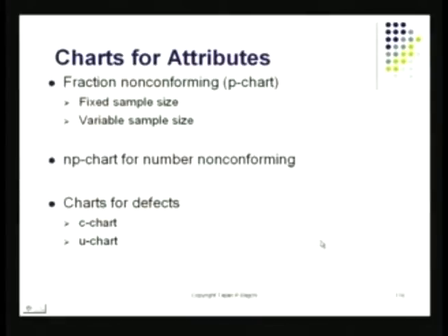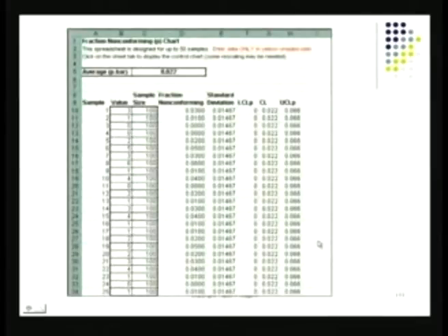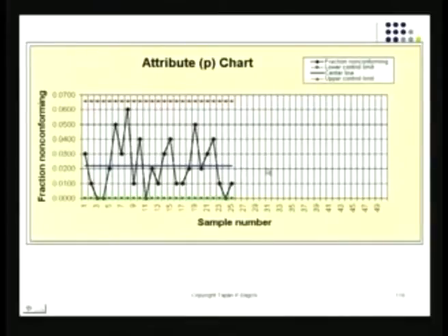Then I've got these attribute charts, and again I can set up an Excel sheet to do this. I key in all my data, I rig up some of the cells with the appropriate formulas, and I have these formulas because I know where they come from. I open the book, I plug in the right quantities. I refer to some cells where I've got the references, and I'm able to get my control limits. Once I have my control limits, I have my regular reading there. I can do my comparison quite easily. Once I do that, I can construct my P chart without any trouble at all. The P chart also can come out of the Excel sheet.